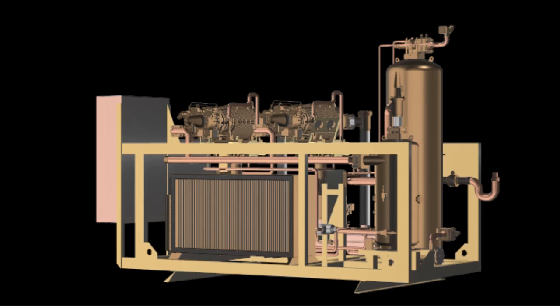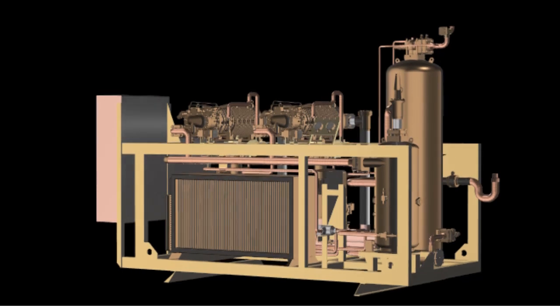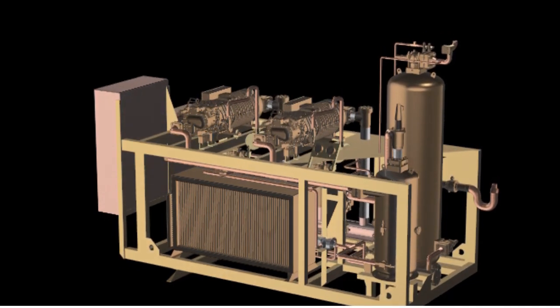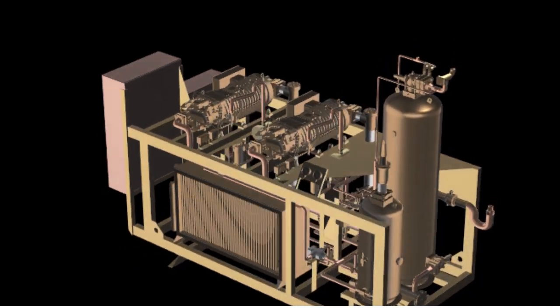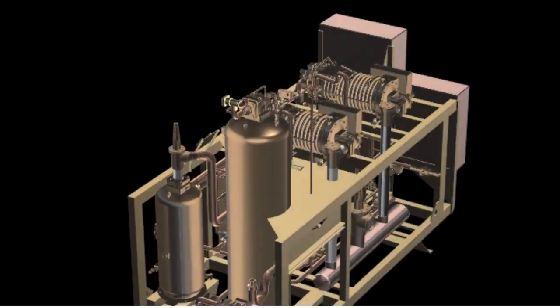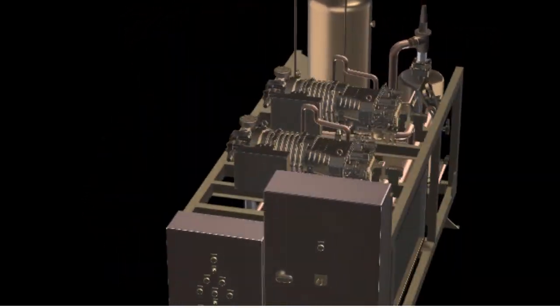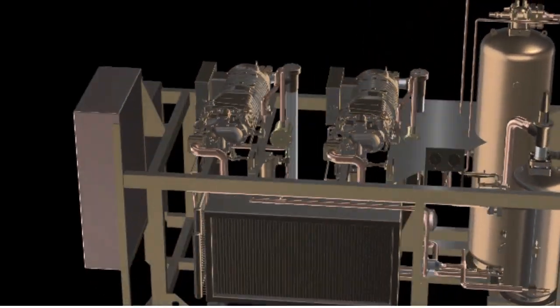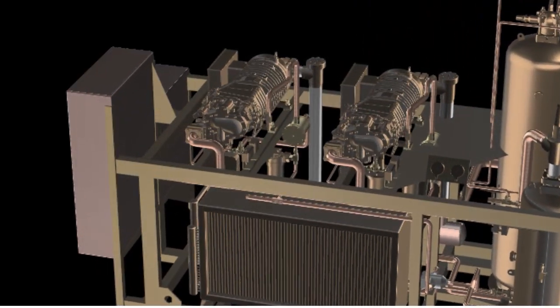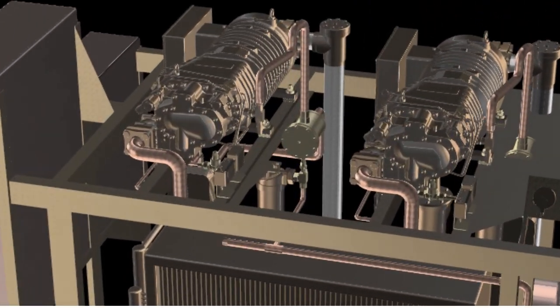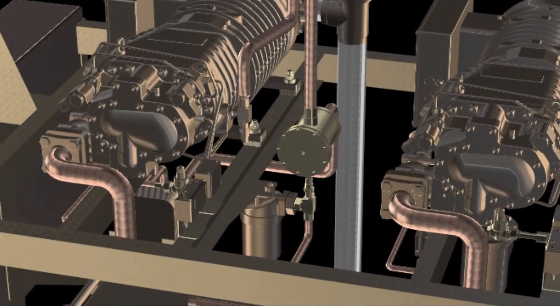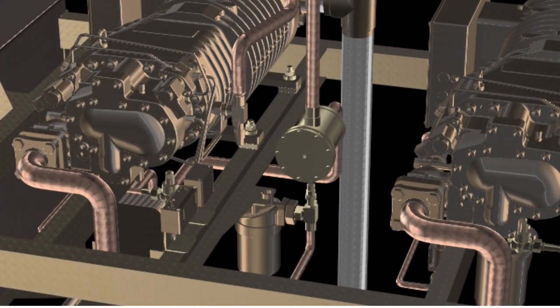Welcome to example 5. Here we have a hydrogen compressor installed in a freely ventilated outdoor location. Hydrogen is a highly volatile and explosive gas that is less dense than air. Of all components in this assembly, compressor seals are at a medium to high risk of leakage, so we will base our classification design on a compressor seal leak.